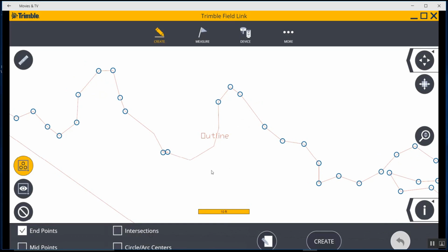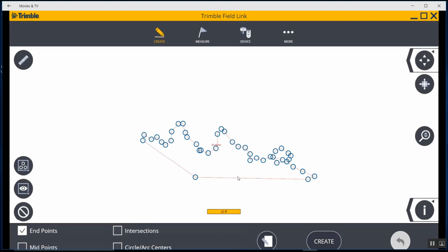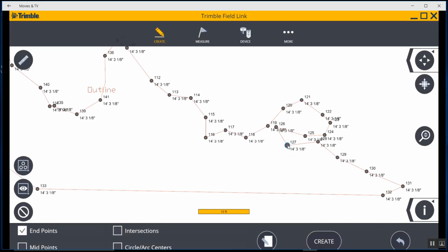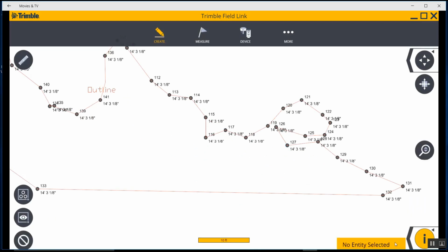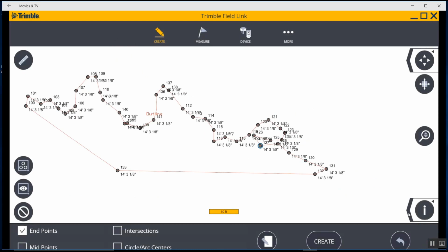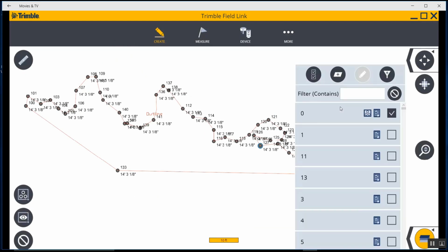And you can also create this in our Trimble Field Points Creator, where you can follow a patch. So if you didn't want to do this on the field tablet, you can do it automatically. But this is a pretty simple area for me to do. I can just click on this point here now. It's a 127, and you can see that each of these individual points has an XYZ coordinate that's relevant to my job site.